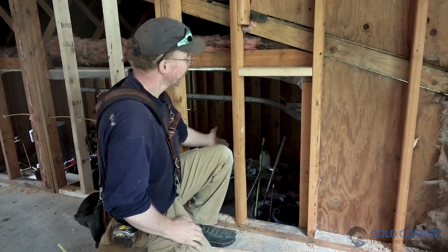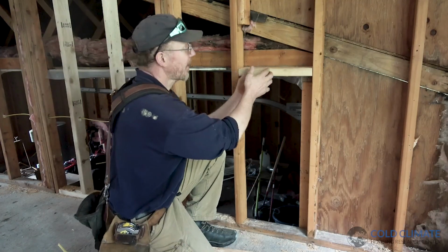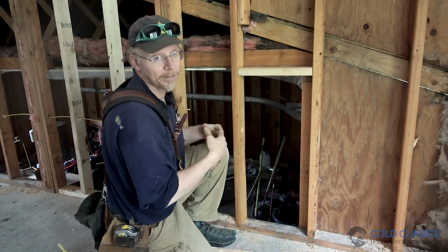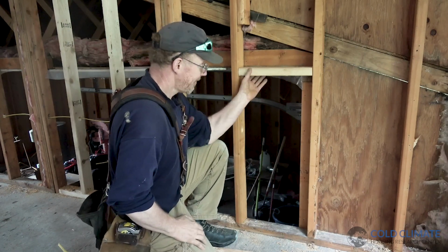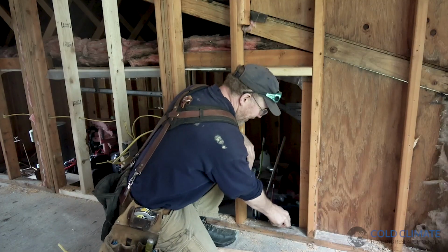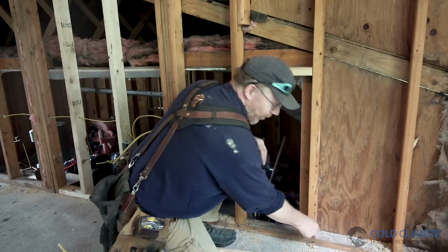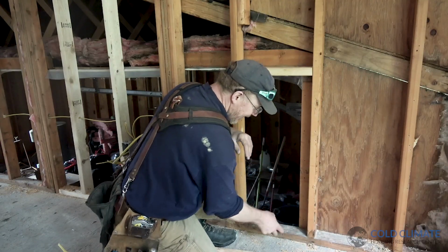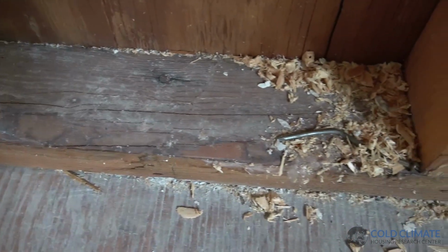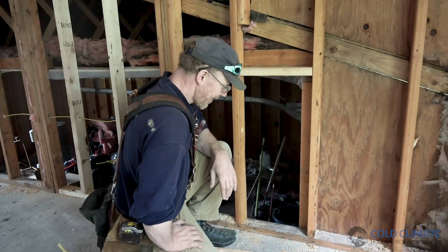You know, we don't want carbon monoxide getting into here either, and we want fire blocking. So our air sealing blocking is serving a lot of other purposes in this case. I look at this old wall and I look at the bottom plate, and as it was built, it's been leaking air for years and moisture's been depositing on this plate. It's still sound, but the nails are rusty, and there's just a lot of evidence of decades of air leakage.